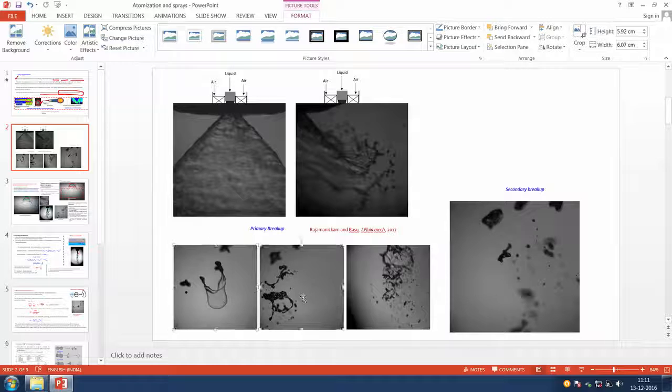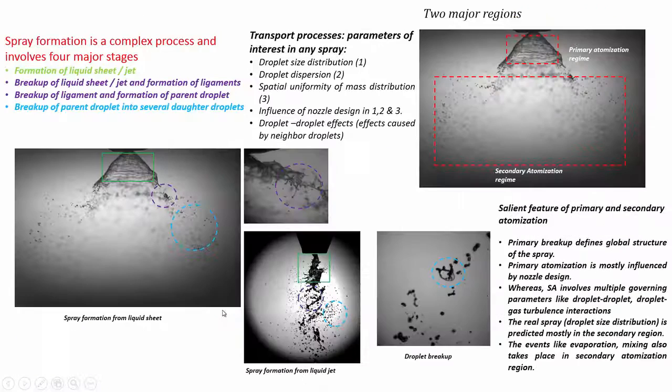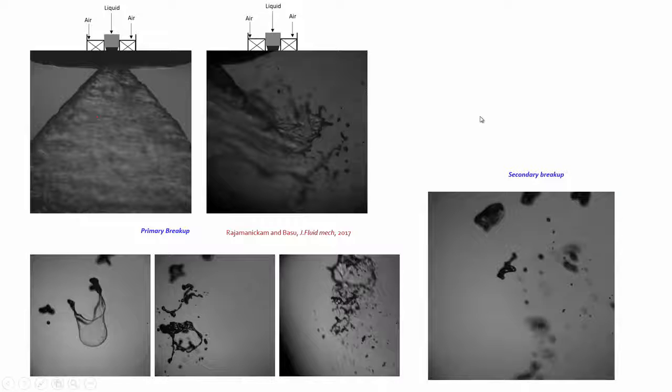And there are some images like this that you see over there, where you can see these small droplets over here, say for example, these droplets, if you look at the cursor, may still be spherical, but you can see these are ligaments. These are long ligaments, and this is like a bag of liquid which is actually bursting. These are different shapes. So all I want to emphasize over here is that the spherical shape of a droplet is not a given thing.